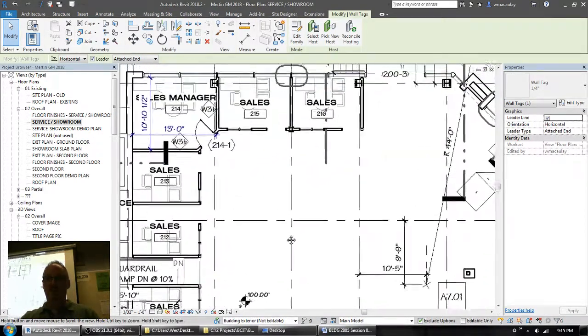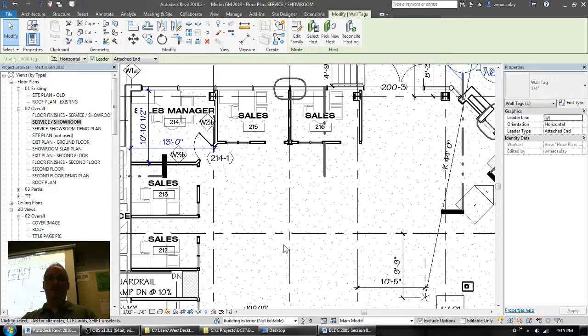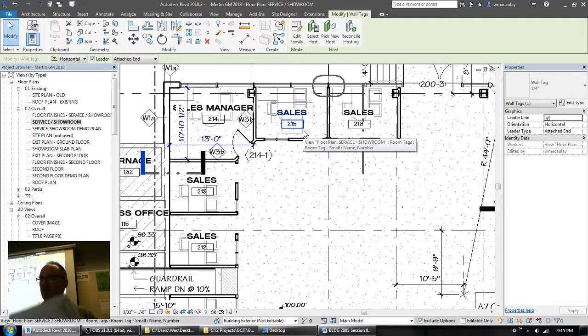So for something like a travel distance scenario, what you want to be able to do is draw a line across your screen that indicates the path of travel, make it traverse as you need it to do in the room, and then finally get to your exit doors. So whatever that length is, you want Revit to be able to total it up and put it into a schedule somewhere so that we can make that happen. Whereas with project parameters, you can't create your own and have them scheduled, but if you use this shared parameters business, it works. Now it's a bit weird, so that's why I say it's a bit of a different animal.